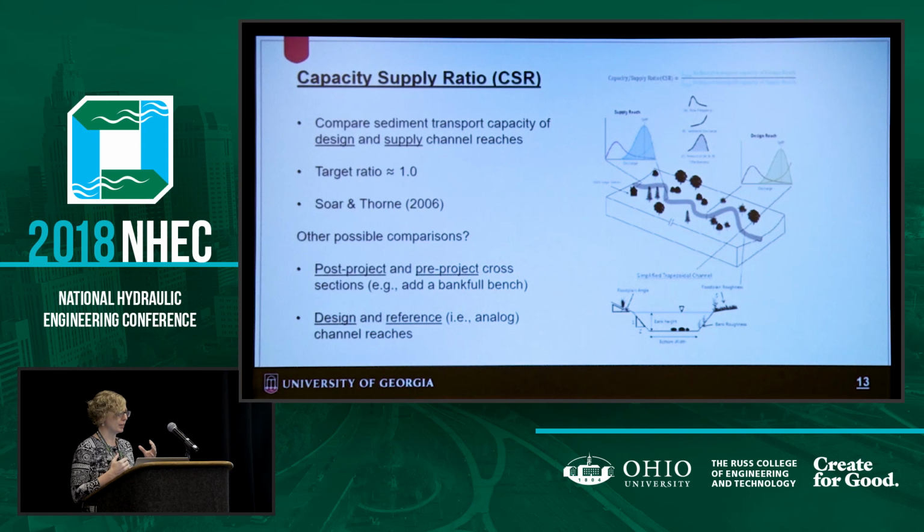This is actually not a brand new idea. There was a U.S. Army Corps publication back in 2006 by Soar and Thorne talking about CSR. There are other possible channel comparisons that you could do. You could do a pre-project and a post-project analysis at the same section. So if you add a bankfull bench to see what the effect would be. You can do this if you have a design reach and a reference reach, if you're using that natural channel design methodology for stream restoration, for example. If anybody's familiar with the Rivermorph software, the PowerSed module inside of that, that's how it's working. It's using a channel comparison between 2 sections.